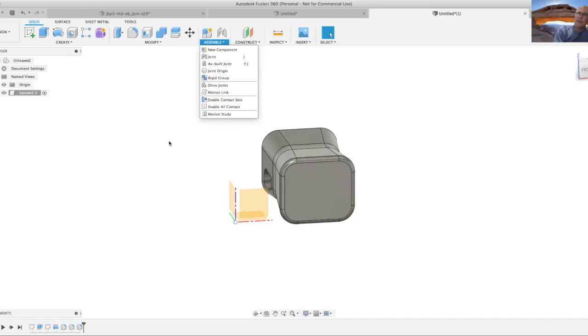And that complex surface would be the equivalent of a body? It would be the skin of a body. Once you make it solid, then it'll be a body. Okay. So if you bring it in and the translation is clean, you can solidify it. Got it. If you bring in a STEP file that's been saved as a solid file, generally the STEP file will come in.